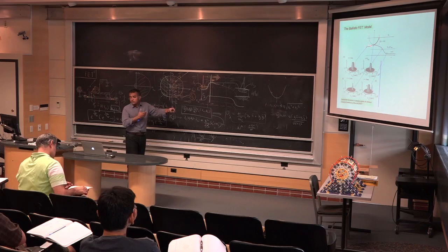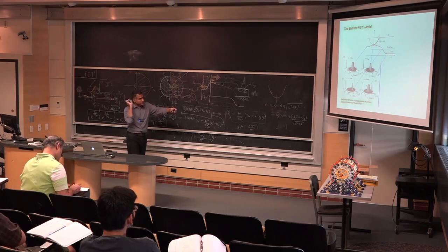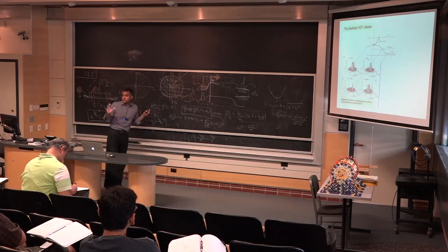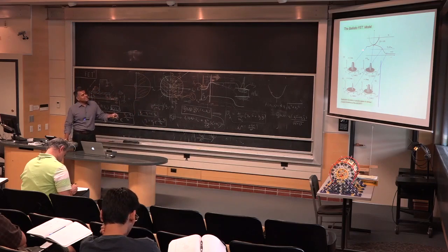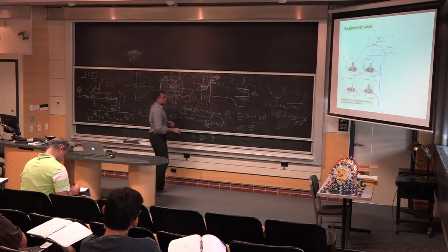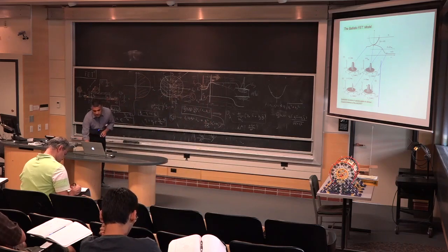Here, there's no chance for the electron to relax. It just shoots, and then it lands in the drain, and all the heat goes there. There's still dissipation. Ballistic means no scattering in the channel, but there is a lot of scattering in the drain. Once it reaches there, it reaches equilibrium with it. So that's the picture now, and I think you can look up those slides.